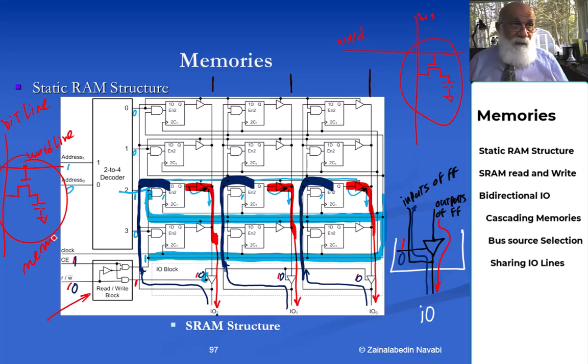Okay, in this situation here, the one I'm showing here, you don't need a clock for reading, or you don't need a clock for writing. For writing, you just hold the address long enough for the data to be written. For reading, the same way, you provide the address and you wait for some amount of time for the memory to read that capacitance value and put that on the bit line so it can be sensed by sense amplifiers on this output here.